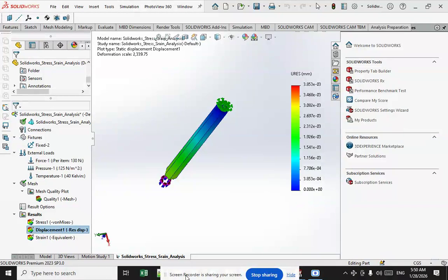The stresses in the structure can be determined by making a model of the structure from such a photoelastic material. The next one is dynamic mechanical analysis, a technique used to study and characterize viscoelastic materials, particularly polymers. The viscoelastic property of a polymer is studied by dynamic mechanical analysis, where a sinusoidal stress is applied to a material and the resulting displacement, the strain, is measured.